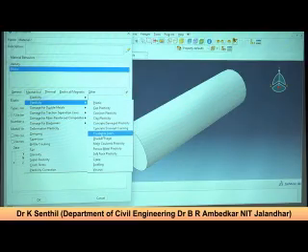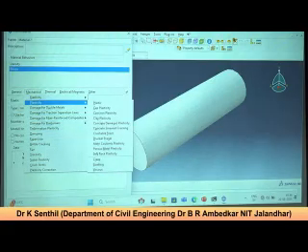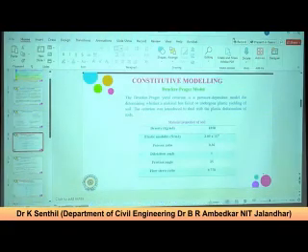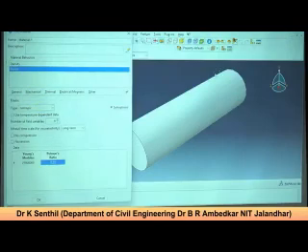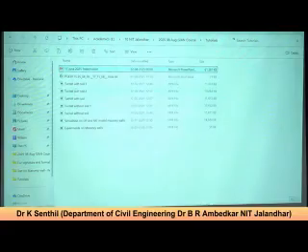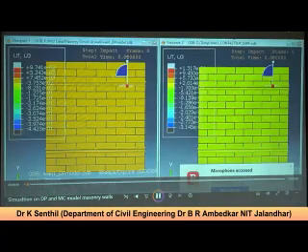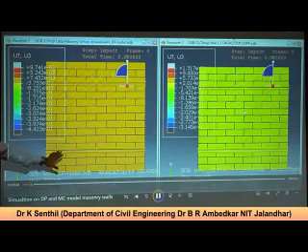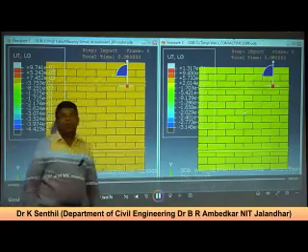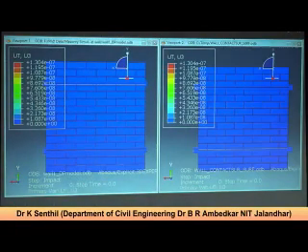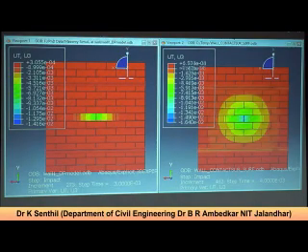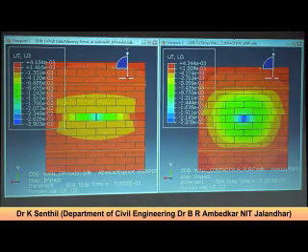You can choose any one, either the Drucker-Prager model or the Mohr-Coulomb plasticity. For example, we actually used both models for masonry walls because they are clay brick walls. I'll show you videos. It just takes maybe a couple of minutes. You see here, this is the DP model, the Drucker-Prager model. This one is the Mohr-Coulomb model. So you can understand the difference in the failure pattern. It's made of clay brick wall panels. Okay, you can say this is the wall we use.